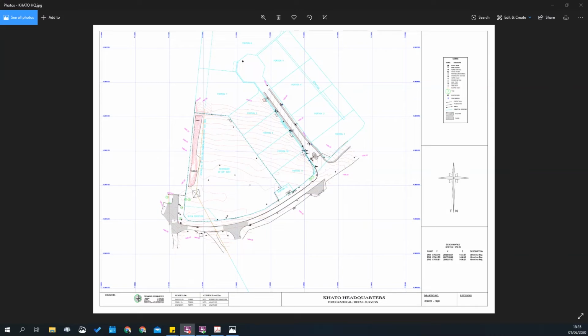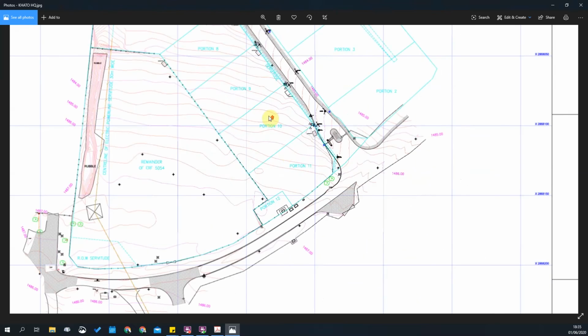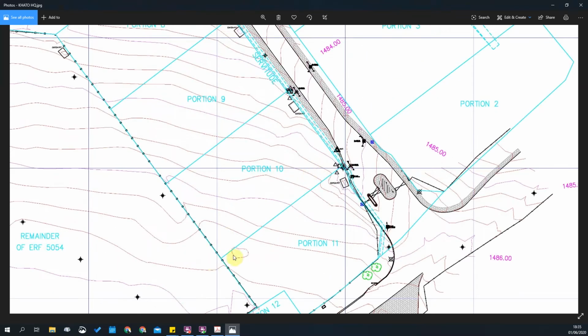In this tutorial, we're going to cover making your topography and your site information from an image. This approach is slightly different, and I'm going to cover creating a topography for a site and for one building. So in essence, you can combine your site information with your building. If you have multiple buildings on the site, I recommend that each one has its own file and that the site information is in its own project file.